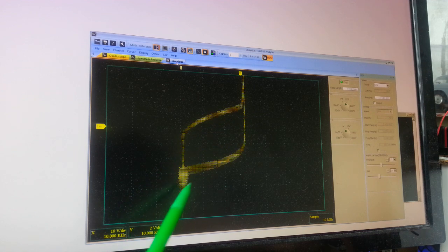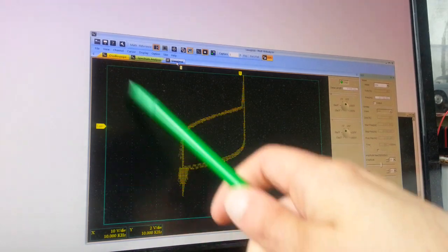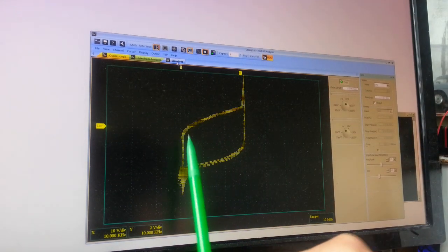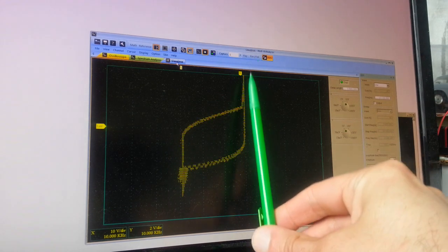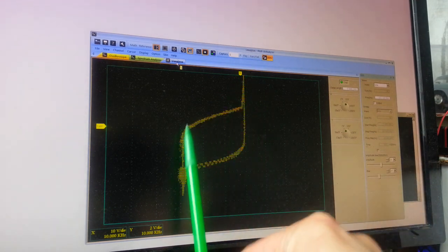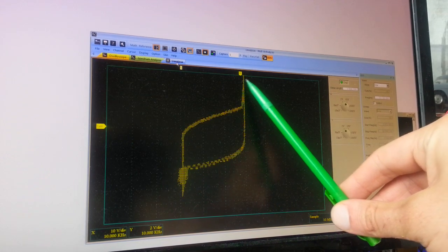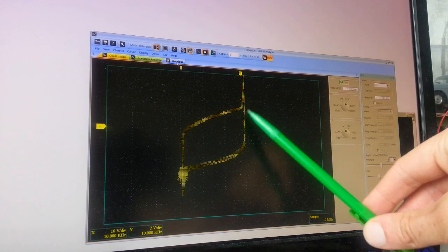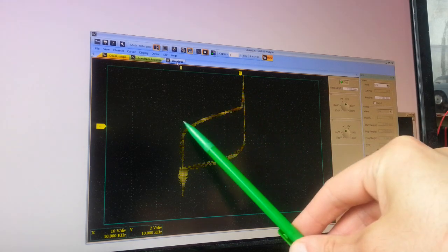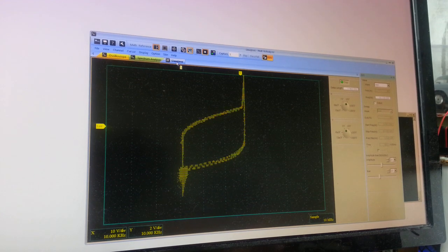So now we have this thing. The voltage is across the x-axis and the current is across the y-axis. So we see that we have those two limits. This is for the open diode, and this one is for the closed diode. And here is the line, it's going like this. But actually what happens, we have a small hysteresis. The curve goes like this in one direction and then goes back over this path back to the initial state. So this is pretty strange.